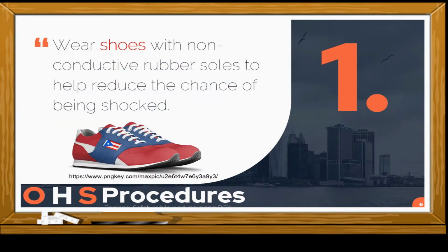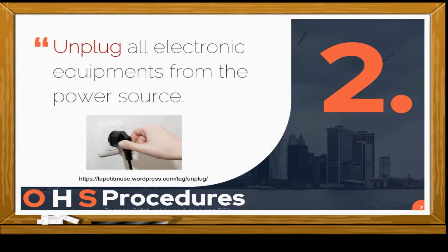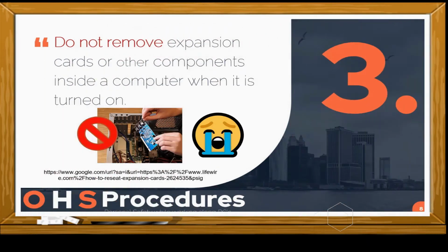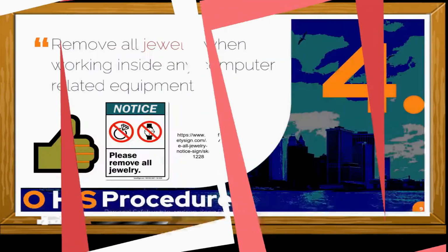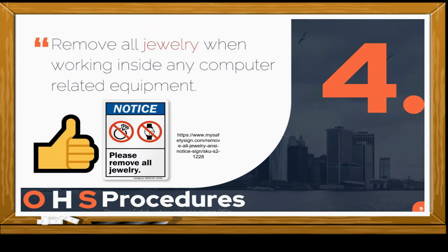Number 1. Wear shoes with non-conductive rubber soles to help reduce the chance of being shocked. Number 2. Unplug all electronic equipment from the power source. Number 3. Do not remove expansion cards or other components inside the computer when it is turned on. Number 4. Remove all jewelry when working inside any computer-related equipment.